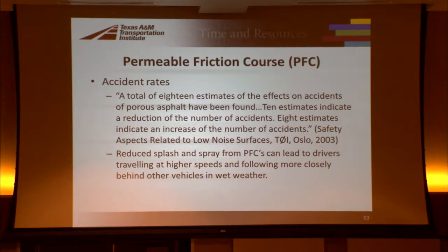The other thing I want to discuss, which I found from a maintenance supervisor in Fort Worth, is that when we started building these, the accident rates went down, but then he started seeing an increase in wet weather accidents, high-speed wet weather accidents. What we surmised is that in some cases, yes, there's a reduced splash and spray, but there's so much of a reduction that people started driving faster and their following distances maybe came closer. So it kind of encouraged this behavior.